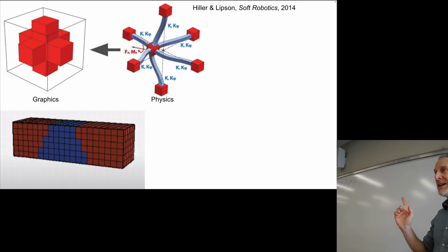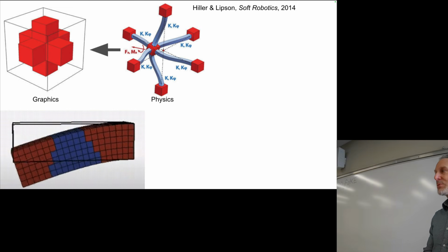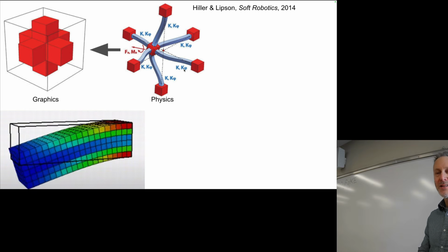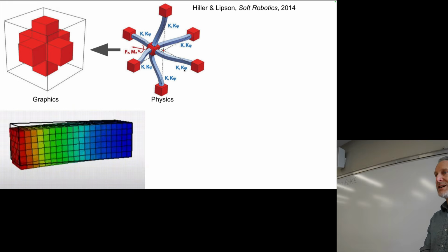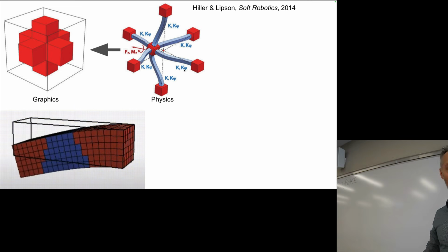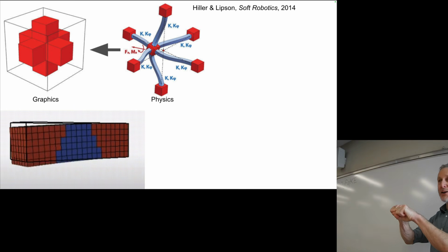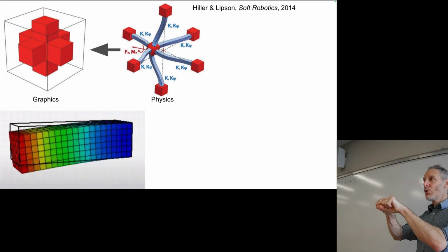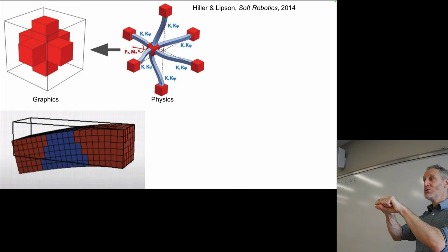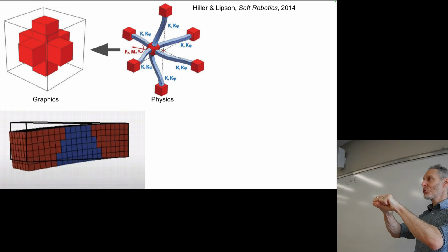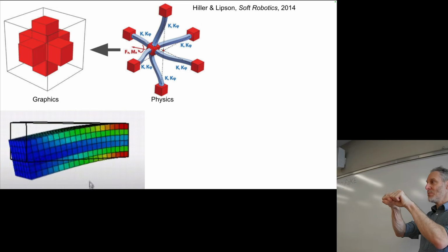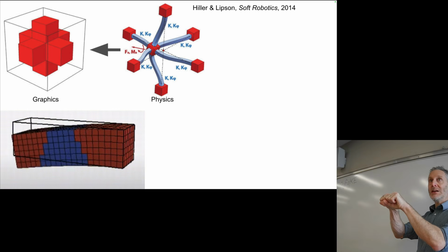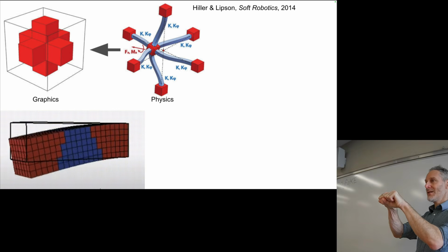Remember that K and K sub phi represent stiffnesses. K contains 3 stiffnesses and K sub phi contains 3 different stiffnesses. K, let's see if I can get this right now. K represents how much a beam resists relative motion of the 2 ends of the beam. So there's 3 possible ways the 2 ends of the beam, which I'm going to represent with my 2 fists, can move, change positions relative to one another. This,